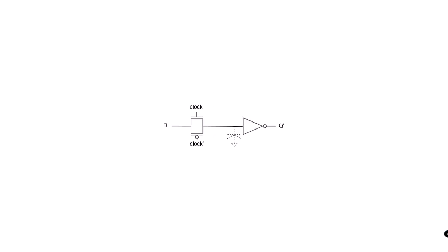Here's a simple form of a CMOS register known as a dynamic latch. The gates of the transistors in the inverter provide capacitance that can be used to store a value. The inverter also amplifies the output signal. The latch's output is inverted from its input value. Access to the storage capacitance is given by a transmission gate. That's the combination of the N-type and the P-type in parallel.